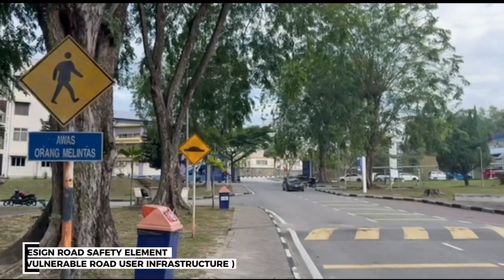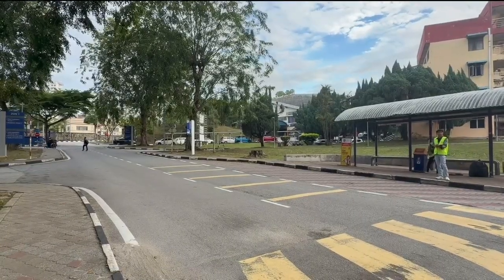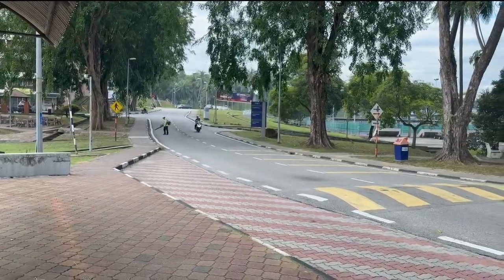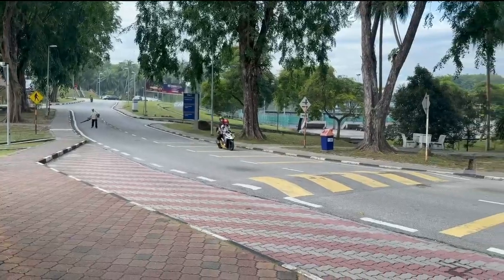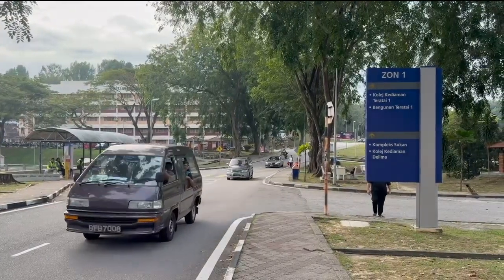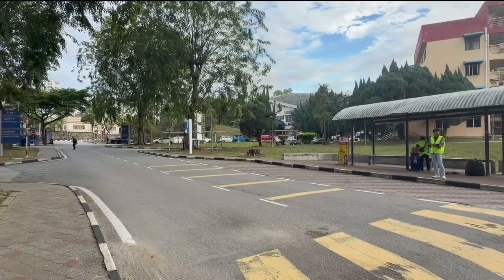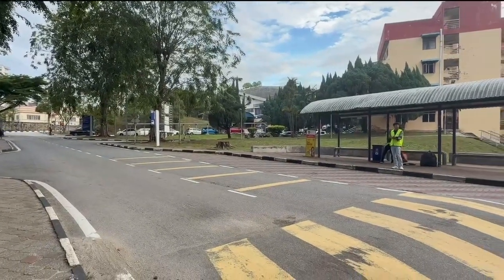In terms of vulnerable road user infrastructure, specifically zebra crossing and road markings, side road markings are present. However, directional movement arrows are not provided. And although a bus stop exists, there are no dedicated bus stop road markings. In addition, no zebra crossing is installed at pedestrian crossing points near the student residential walkways. These deficiencies may cause confusion in vehicle movement and increase potential conflicts between vehicles, buses and students crossing the road.